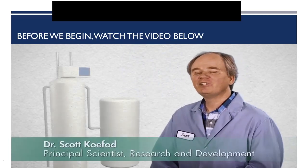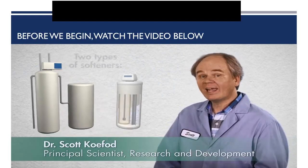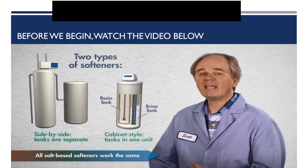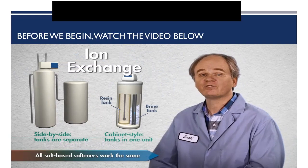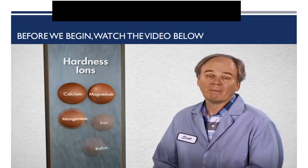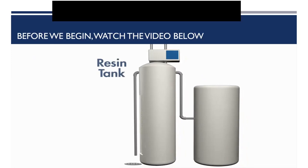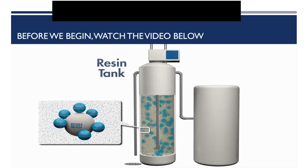Water softeners contain two separate chambers, a brine tank and a resin tank. And the resin tank is where the water softening is actually taking place. Water softeners make use of a process called ion exchange to remove the hardness ions from the water. These hardness ions are primarily calcium and magnesium, but they can also include things like manganese, iron, and radium. The resin tank contains a bed of small beads that have sodium ions electrostatically attached to them.